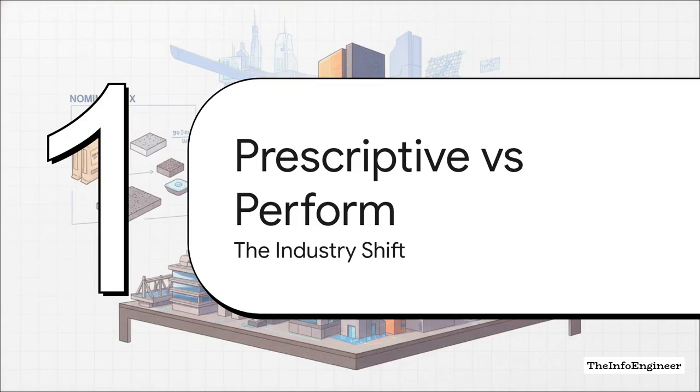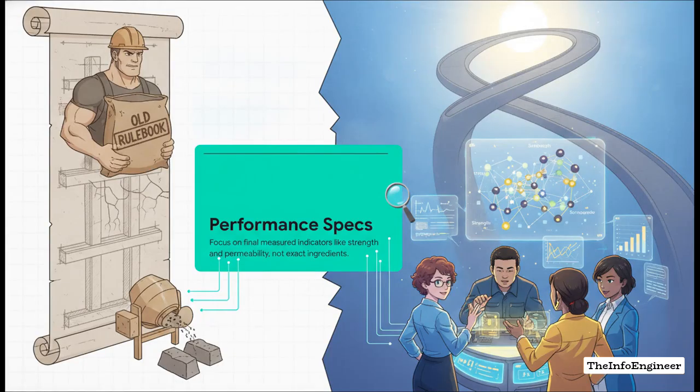Moving on to Section 2, prescriptive versus performance specs. To really grasp why the ready-mix industry is evolving so fast right now, we gotta talk about the specs. A nominal mix is born from what we call prescriptive specifications. These are basically old-school rules that tell you exactly what ingredients to use. They'll demand a minimum cement content, or they'll heavily restrict your use of supplementary materials. Basically, they tell you exactly how to make the concrete.